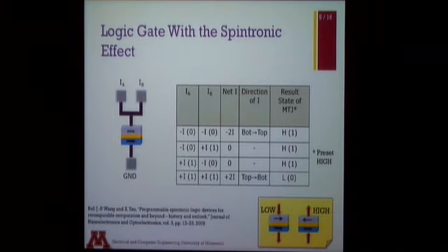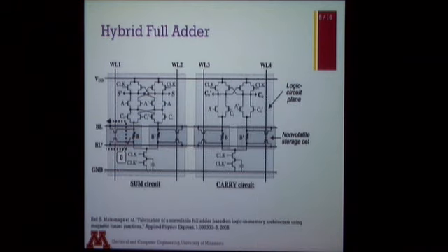They use sense amplifiers to sense the data in the magnetic tunnel junction. That converts it into an electrical signal, and then that is processed through processing circuits. And we'll talk about sense amplifiers a little bit, but before that I wanted to show you one of these interesting papers that was published in 2008. I think it was Professor Ono's group in Japan. And what they did was they used this particular circuitry and demonstrated the function of a full adder.